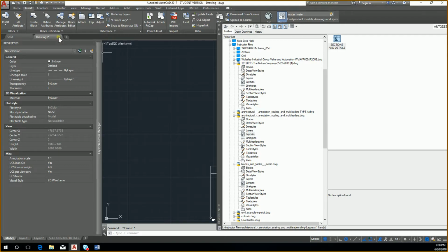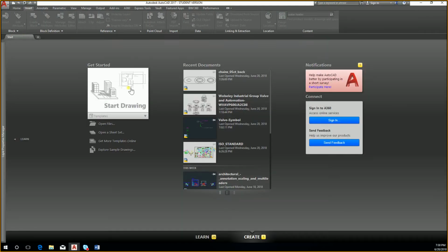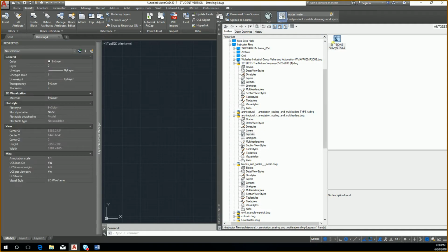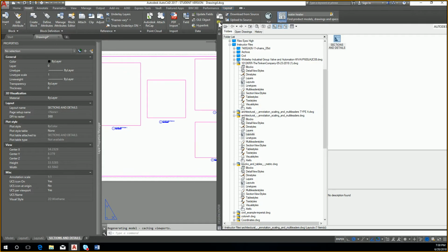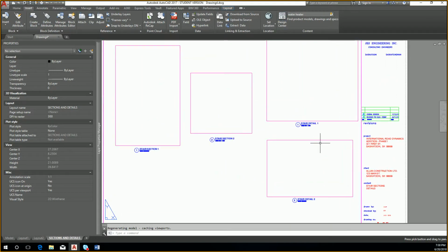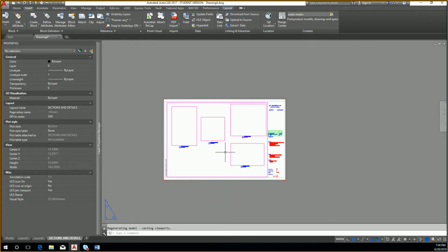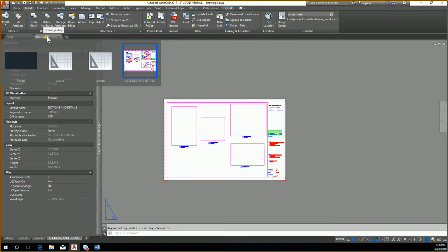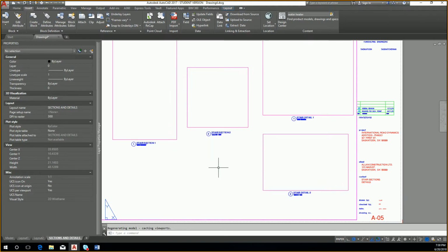So if I jump to a brand new blank drawing, and I bring in a new layer, or previous layer, as you can see, it's already been pre-created. So all those viewports that were made last time in that old drawing that we did, this is that staircase example we did, I don't have to redo it all over again. It's already pre-generated. So all your viewports, all your different namings of the views, it's already all recreated on a brand new drawing. See, drawing 4, just made this drawing. This is already available here for me.